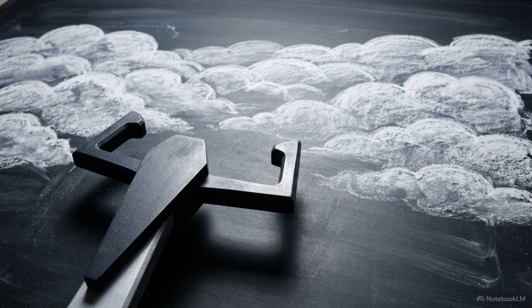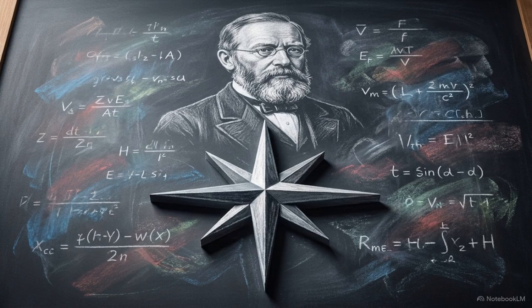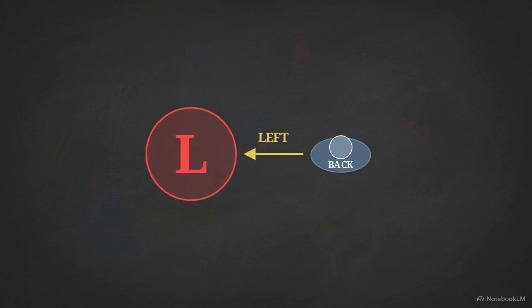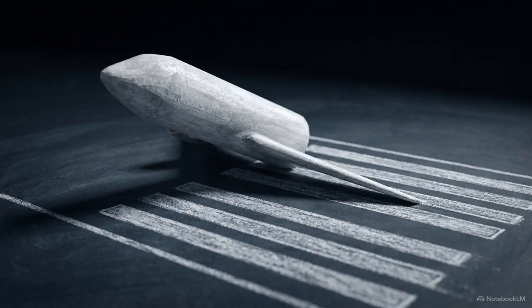We can translate this theoretical atmospheric physics into a practical, actionable rule for pilots in the air. Formulated by a Dutch meteorologist, Buys-Ballot's law states that in the northern hemisphere, if you put your back to the wind, the low-pressure center will always be on your left. This means you can read your aircraft's crosswind drift to orient yourself.